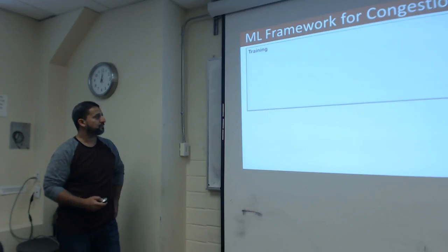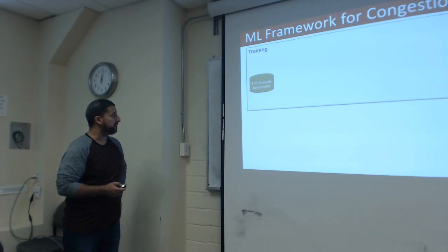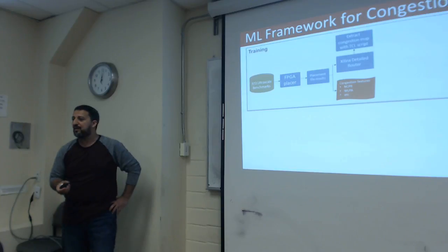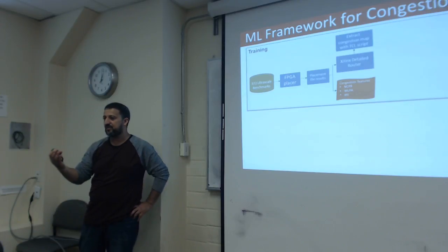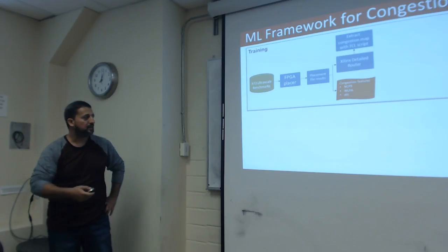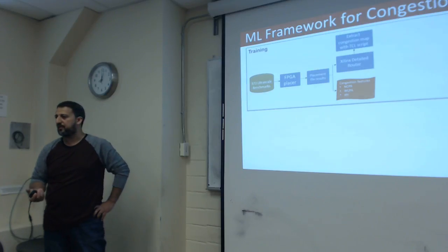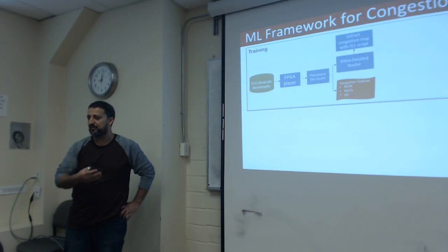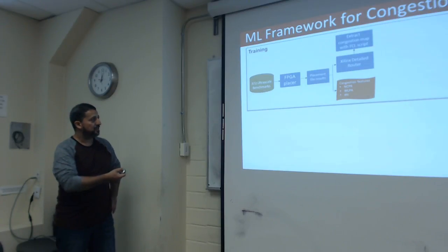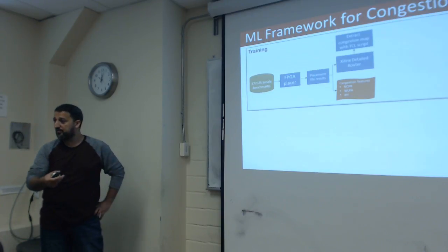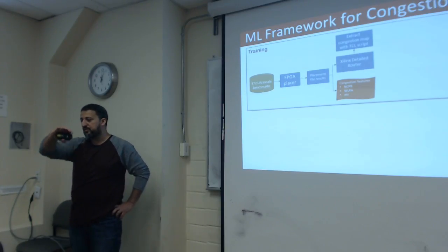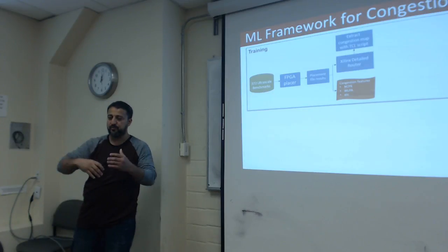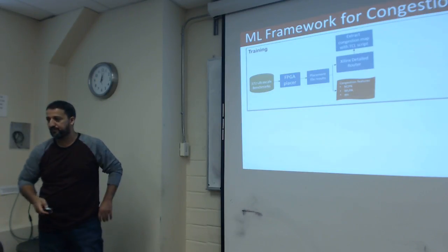Now, we use the 372 benchmarks and place them. We also get the binaries from other teams. So we have different placers and different versions of GPlace, so we are able to get maybe 5,000 different placements. We can do more, but maybe it's enough right now. For those 5,000 placements we extract the features. We run the routing for all of them. And then we write a Tcl script that extracts the routing tree for each net and computes the utilization for each tile or switch. Yes?